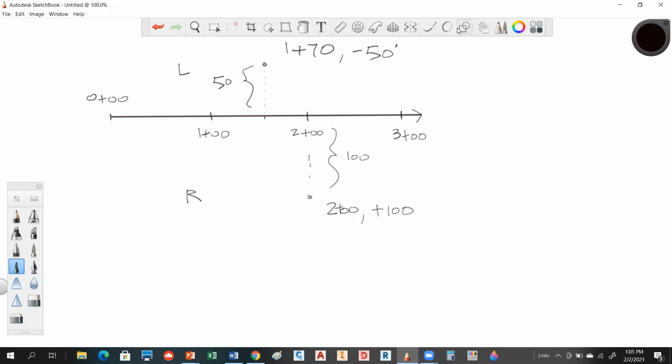So what happens when you get on a curve? Okay, so when you get on a curve, if this is where a curve starts, now things change constantly because now you're measuring along a bent distance. So at this point, this would be 4 plus 00, measured on the bend, and then this would be 5 plus 00.